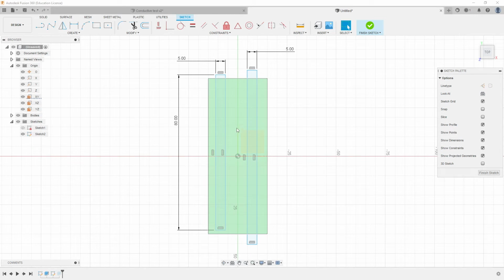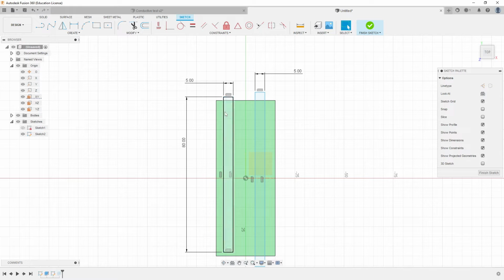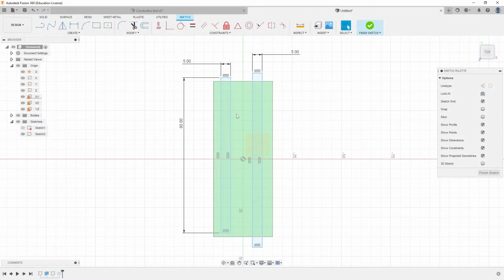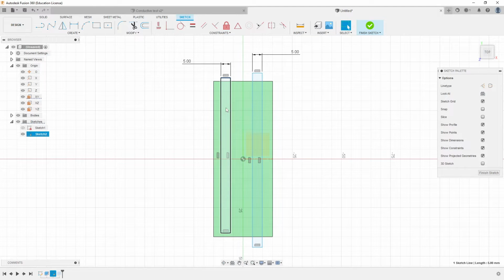What else could we do? Well, what I would like to do is maybe just make this thing right here even with this, because in the first case, even if I were to make this centered right onto here, if I increase the length of the other, this being 80, it's still going to have a problem. So that's no good. So here's what we want to do. We actually just want to get rid of this. And I would like to take this line right there, and I want to make it permanently stuck to this edge. No matter where that edge goes, I want it to track with it, okay?